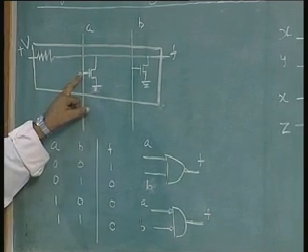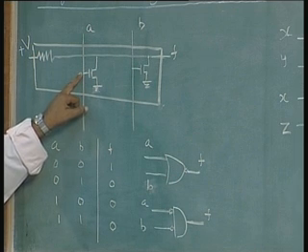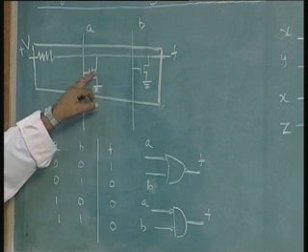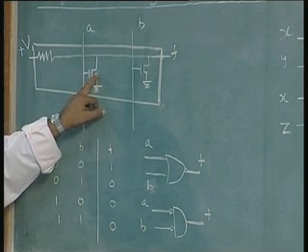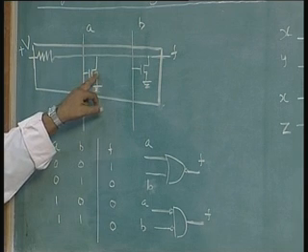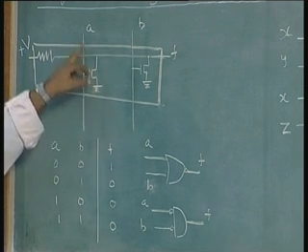So we will only talk about cutoff and saturation region, we will not talk about the triode region, etc. This is not a device theory class. This N channel MOSFET can be turned on or turned off by putting a voltage here. Putting a voltage 0 here will turn off this device, putting a voltage 1 here will turn this device on.